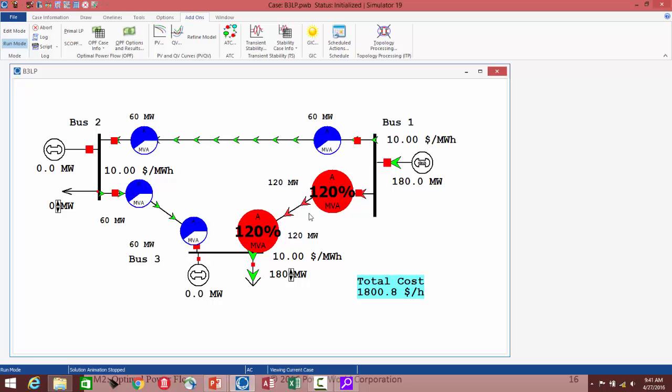So because we're ignoring the transmission constraints, we're not enforcing this, we're getting all the power from the generator that costs $10 per megawatt hour, and the LMP at every node in the system is the same. So you can think of the LMP, or the megawatt marginal cost, as what would the change in cost be to get 1 more megawatt delivered to that bus. And again, if we ignore the transmission constraints, the cost of delivering 1 megawatt to any bus is $10 because you would just get 1 more megawatt from this generator, as long as it's not at a limit, which it's not.